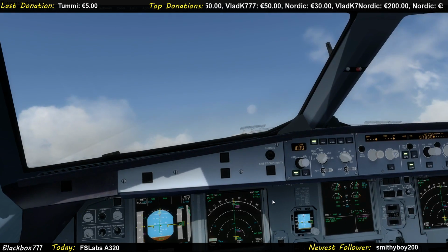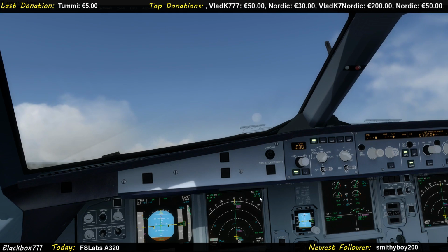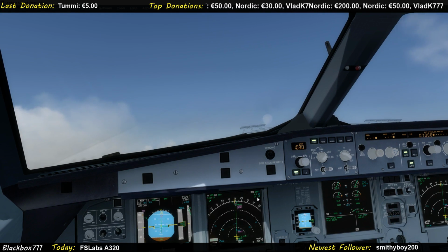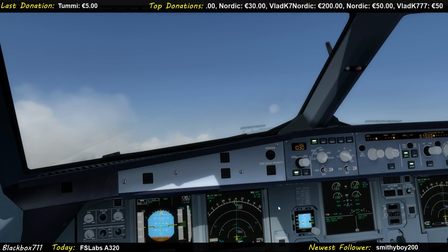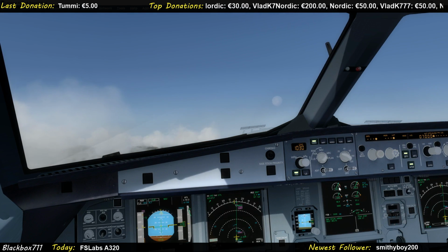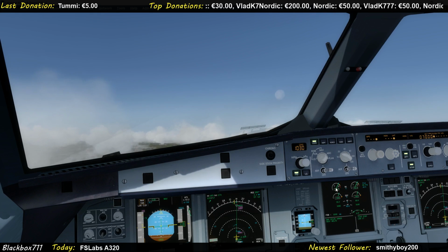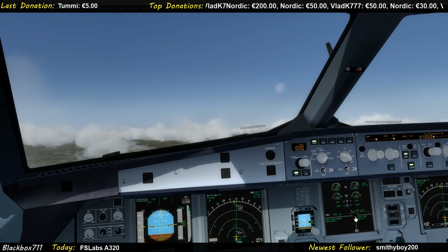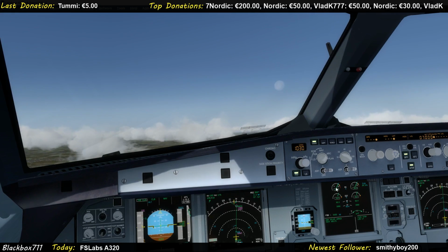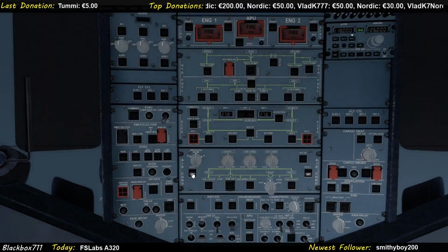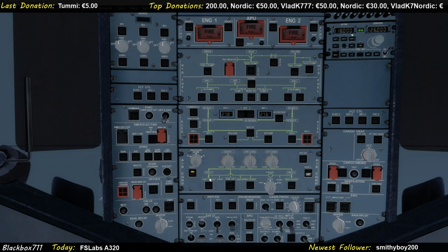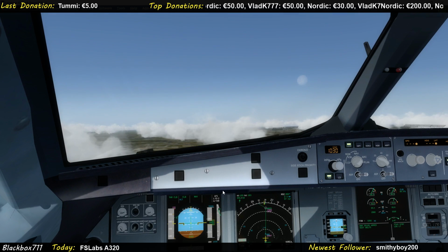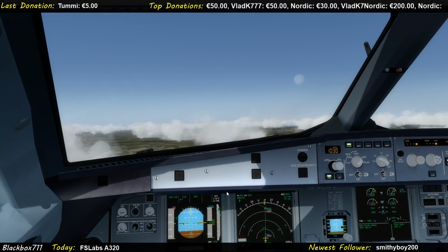Alright, autopilot 1. Yes, you Airbus fan, you would have to wait for the engines to synchronize and have symmetrical thrust. If you go past 50% and you have like a 20% difference of power because of the different spool up times, you would probably do a 360 on the runway, if it's wet and, you know, braking coefficients aren't good. PEX. Yes, I'm on it.